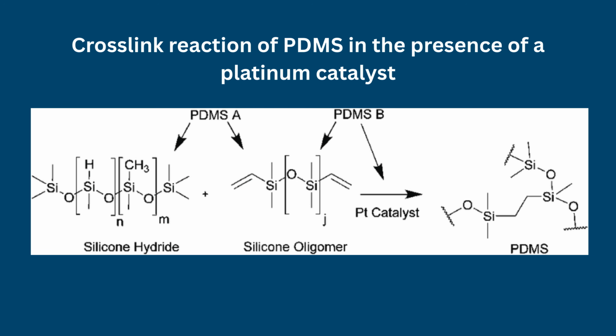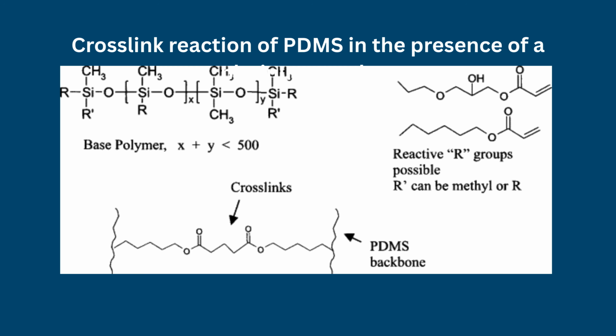Commercial silicone formulations generally consist of PDMS-based polymer, reinforcing fumed silica, cross-linking agent, platinum or tin catalyst, cure inhibitors, pigments, and processing additives. The incorporation of reinforcing silica nanoparticles substantially increases tensile strength, tear resistance, and modulus through hydrogen bonding between silanol groups and the polymer network. Cross-link density ultimately determines hardness, elasticity, compression set, and dimensional stability.